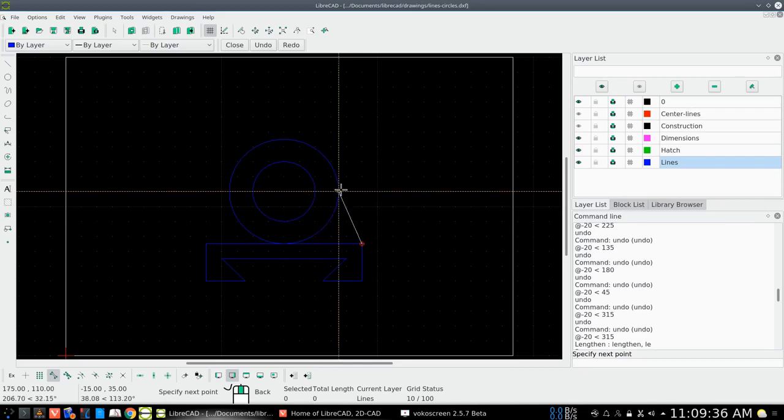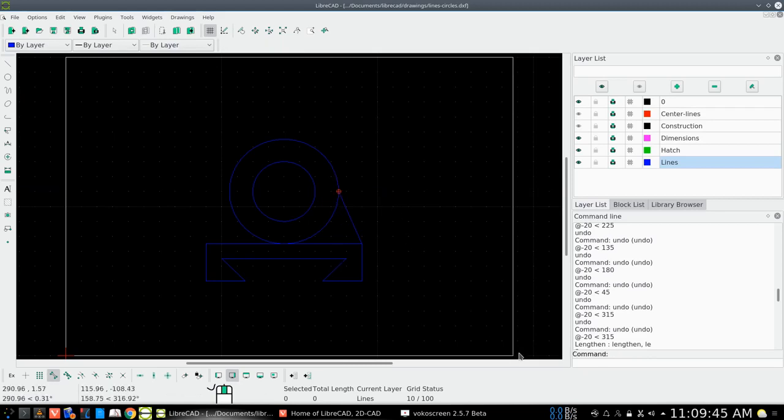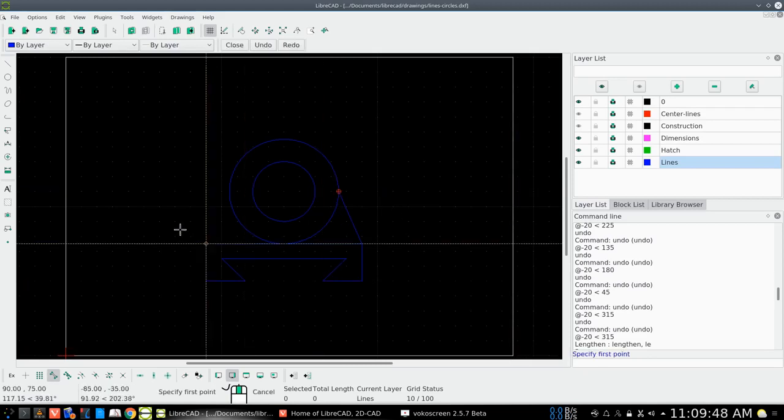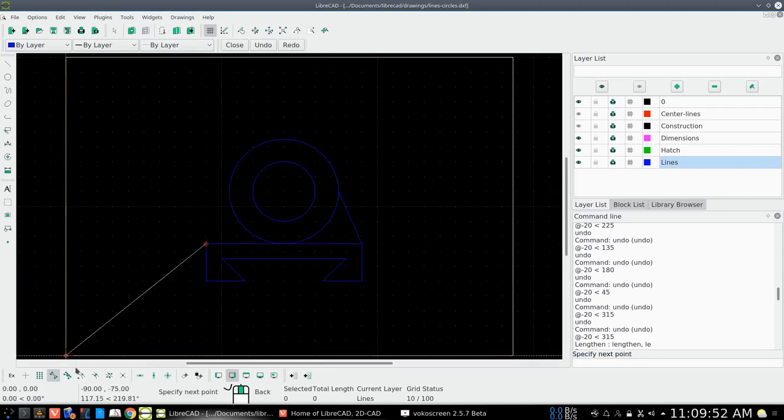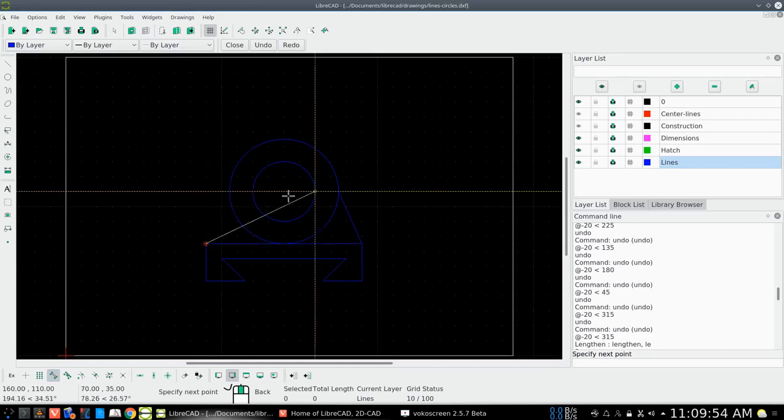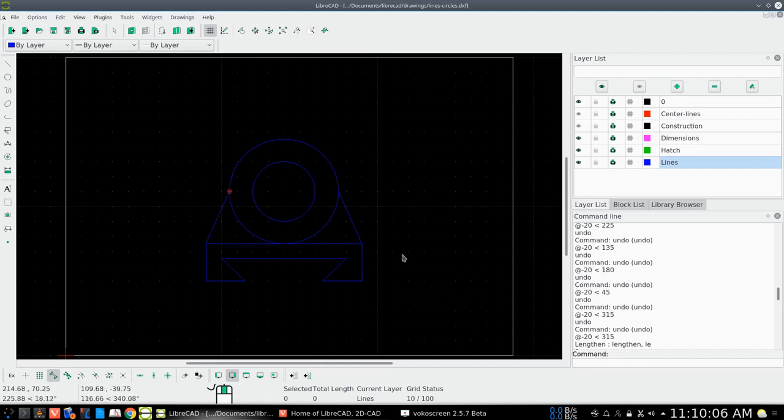Okay, so we can go ahead and just take that, and we'll right click, let's add another line over here, snap on end and snap on end. You see the snap on end, there is a center point here which acts as the end right across, so we snap on that. Let's release that tool. There you go. There is what we are drawing.